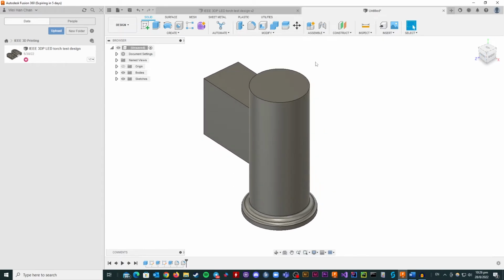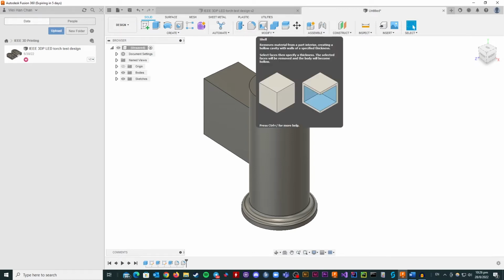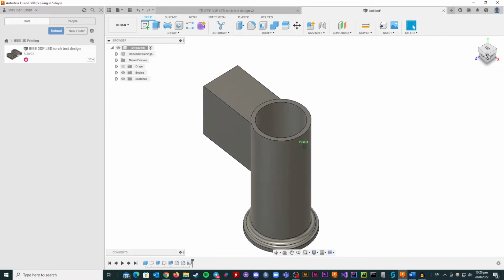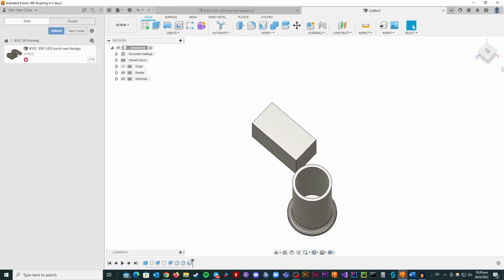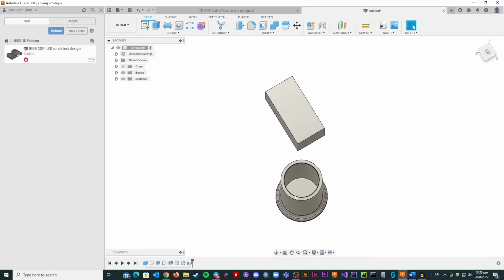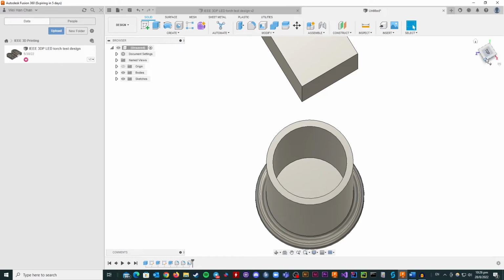And this is one that's actually quite interesting, because what this does is it creates a cavity in a solid object. So you can choose your face, of course, over here, it says face. So select this. Over here you select thickness of how you want the insides to be. So let's say 5 mm. No, I can go even thinner, 3 mm. Press OK, and now you will have what would probably seem to be a pen holder with a certain thickness and a hollowed out inside.